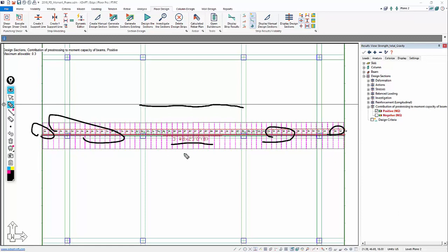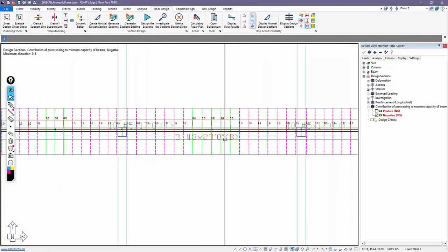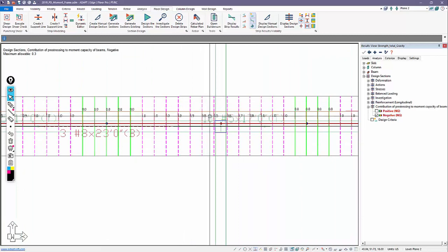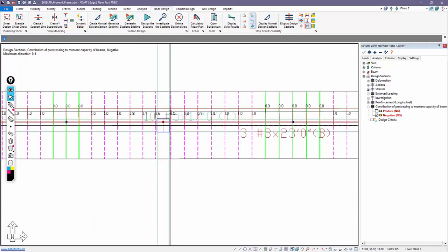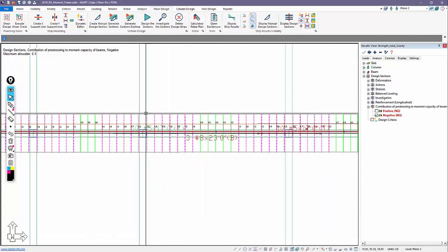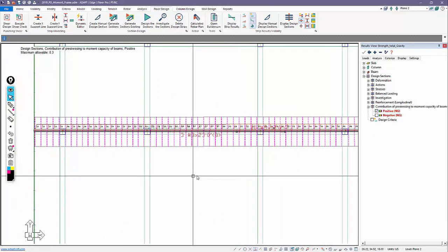So this tells us where we may have an issue meeting this particular provision, or the 25% that we entered at the onset inside of the design and analysis criteria. If we switch this over to negative capacity, again at this location where we have top bars on either side of this long span, we have roughly half, 50% controlled by PT, the other 50 by the reinforcement. So that's the lowest amount controlled by PT.